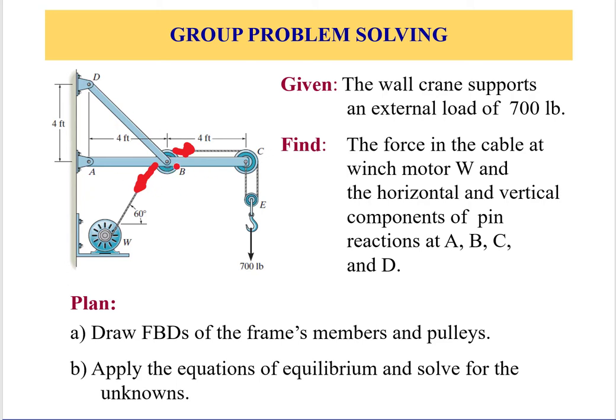With that, we will be able to find the external loads applied on AC, where the loads on that frame beam are the unknowns Ax and Ay, the ones we calculated at B, Bx and By, the ones we calculated at C, Cx and Cy, in addition to T, because this frame is connected to the cable. So let's not forget that T also, which is 350.